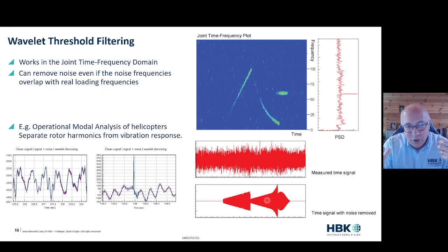So with things like wavelets, we can take out those dominant harmonic frequencies and look far more at what the structural frequencies are for the modes below them. And over here you can see this is a wavelet filter that's removed high frequency noise, but it's also removed spikes as well. So wavelets are difficult to use. It's not going to be an easy filter, I'm not kidding you, but it's really capable when you have it.